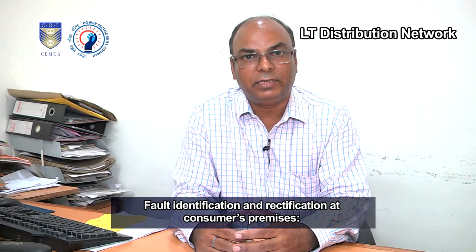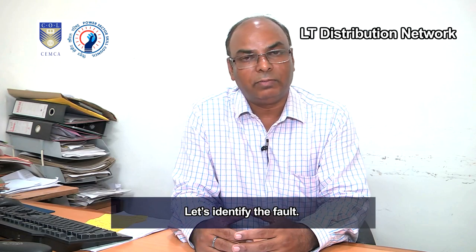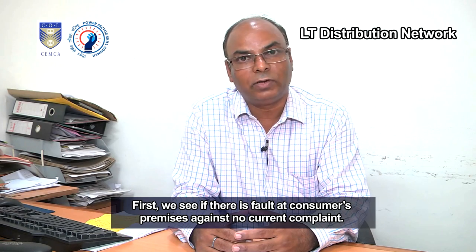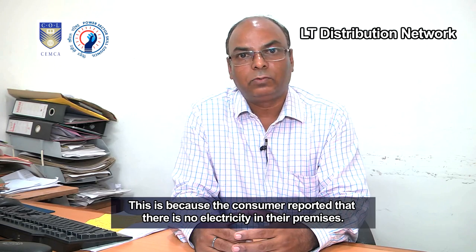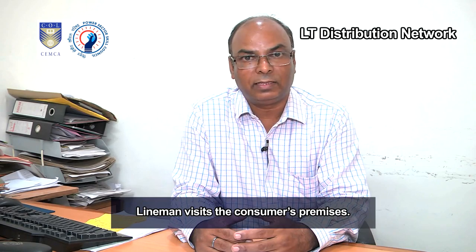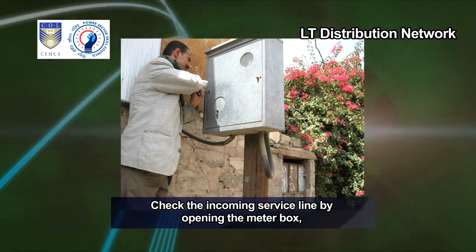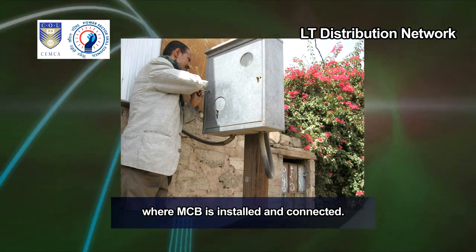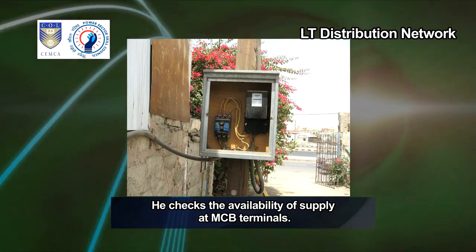Fault identification and rectification at consumer's premises. Let's identify the fault. First, we see if there is a fault at the consumer's premises against a no current complaint. This is because the consumer reported that there is no electricity in their premises. Lineman visits the consumer's premises, checks the incoming service line by opening the meter box, where the MCB is installed and connected. He checks the availability of supply at the MCB terminals.